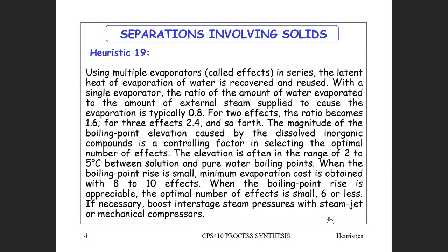I've got to increase the sugar concentration in this stream that's coming out of my fermenter. How do I do that? I will use multiple effect evaporators. So it's important that you know these heuristics essentially off by heart, so that you've got a library of heuristics in your head. You can say, oh, this is where I should be applying this heuristic, and then you go ahead.